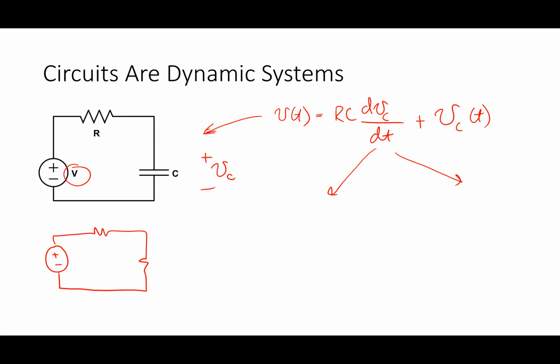The transient and the steady state. Yeah. So I'd have the steady state piece, and then I'd have the transient. The transient always consists of a bunch of exponentials. So I'd have an e to the negative t over tau, and if it was a higher order system, there'd be more of those exponentials. And the steady state would be based on whatever the input is.